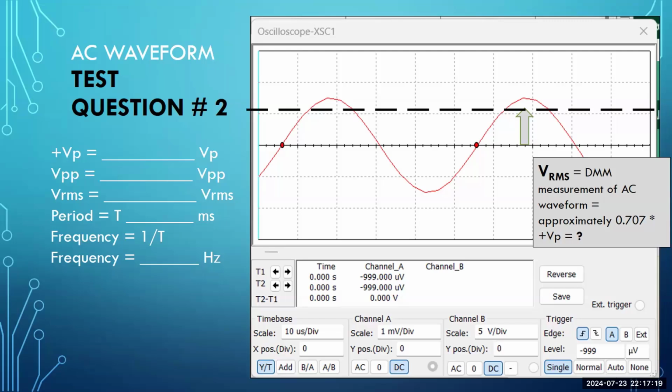So here's something that might help you out. If you look at this, my red dot does not start conveniently at the intersection of the 0 volts reference line and one of the major division lines. Too bad. You are shown that it does land on one of the minor horizontal division markers. And exactly how many is this going over to the next major division marker? Looks like 3 spaces on this side. Looks like 2 spaces on this side.